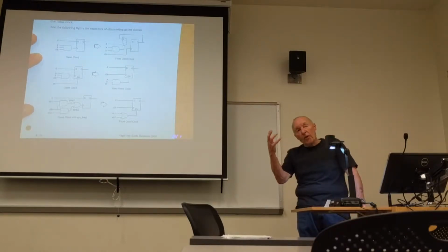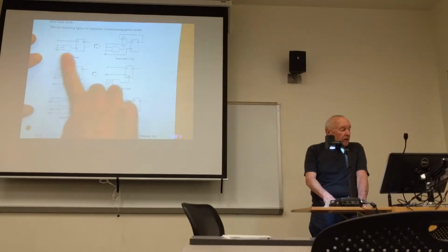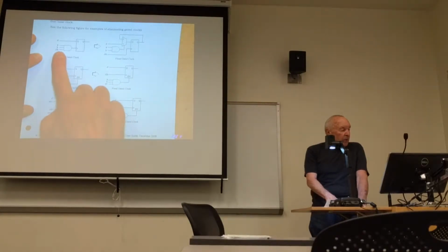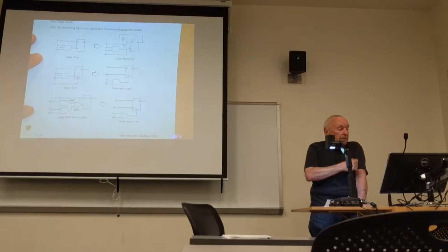So you have some sort of gate signal that controls when the clock signal actually gets applied to the clock input on the register. So in this case, A and B both have to be logic 1s in order to get clock pulses to this register. Here is the preferred solution, and this is the way that you should code your Verilog modules if you need a gated clock.